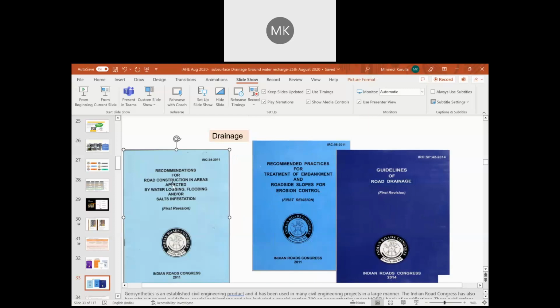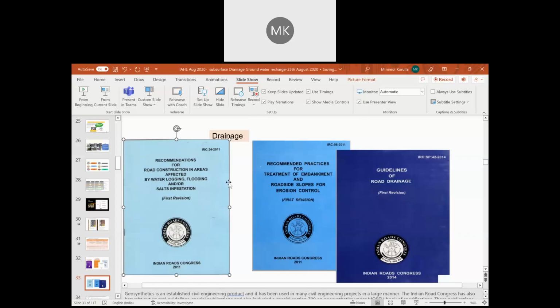So the drainage composite, again, the application: instead of at the junction between the subbase and subgrade, we may use it as a part of the subbase. We may use it as a part of the subbase, and we can drastically reduce the subbase thickness, and in some cases the entire subbase can be replaced by the drainage geocomposite.